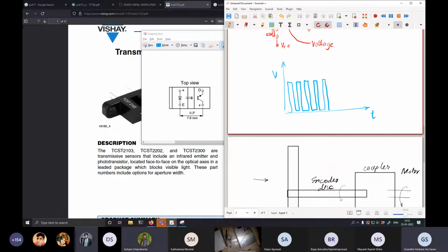It's a very easy question. So by looking at the number of pulses, the frequency, the peaks and time. Yeah. So you know the time division. So how many peaks are there per time division? Instead of taking only one peak, you can take averages of 5 peaks. All right. Good. So this would be one of your tasks. And now I will show you the actual circuit in action. Before I sit down again, any doubts?